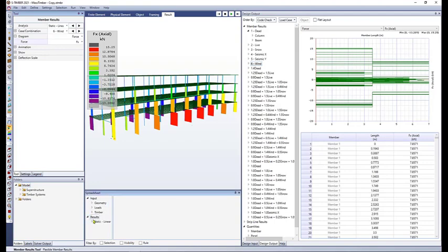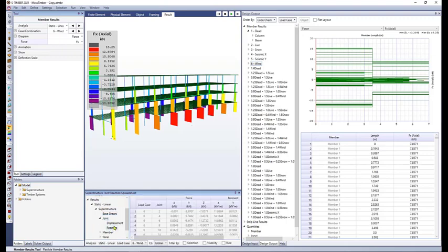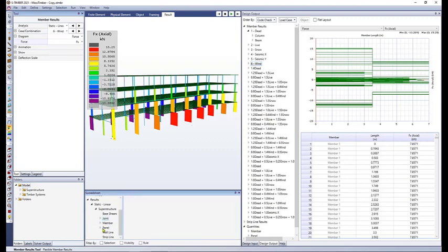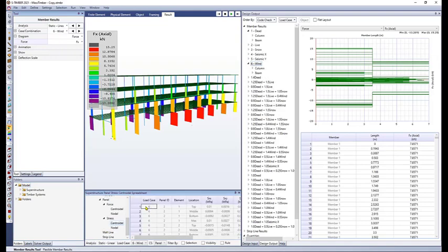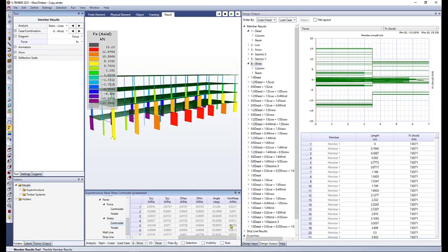If you go to the results, static linear analysis for the superstructure, you can check information such as the base shear, the forces in the joints, displacements, reactions, members, panels. All that information is right here. And the good news is that you can copy all these tables in a spreadsheet format such as Excel for later use.